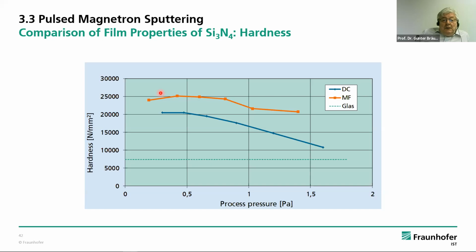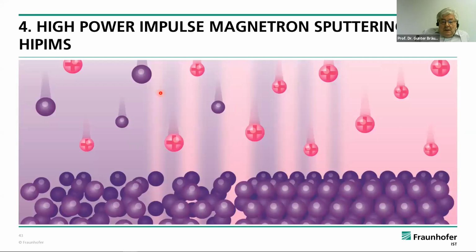And in this case, with the sputtering, of course, you can apply the mid-frequency. Like Günter mentioned, you can have a sine wave, or you can have the rectangular shape of the sputtering cathode. In the rectangular shape, you can even add some bipolar sputtering, some positive overshoot to discharge your cathode, mainly for the single cathodes.